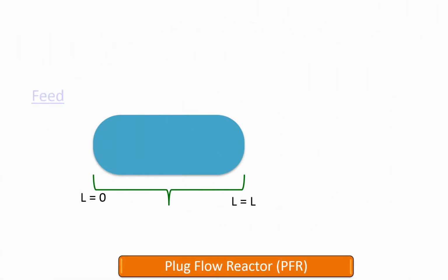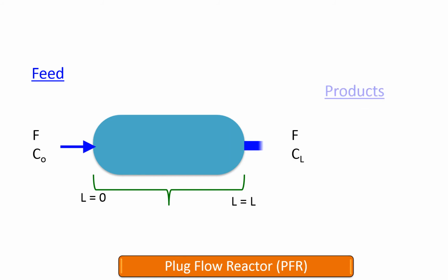This figure illustrates a plug flow reactor, the second type of continuous flow reactors. It is an unmixed reactor and the flow is orderly, with each element or slug of fluid not overtaking or mixing with another element or slug ahead or behind.